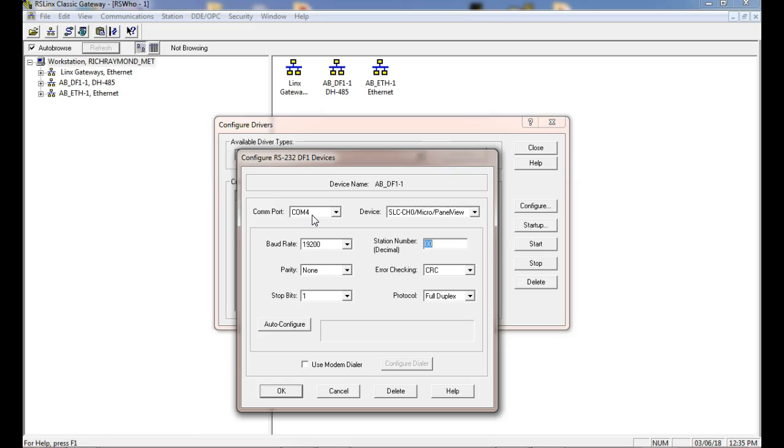But what's happened with baud rate now is baud rate is the number of transitions of the carrier. And then what we do is we modulate the carrier to carry the amount of information. We've got several ways we can modulate the carrier that we won't get into. But sometimes it's kind of misleading. So you might be running 3,000 baud, but you might be sending 12,000 bits per second. Does that make sense? Because they let more than one bit ride on a carrier.